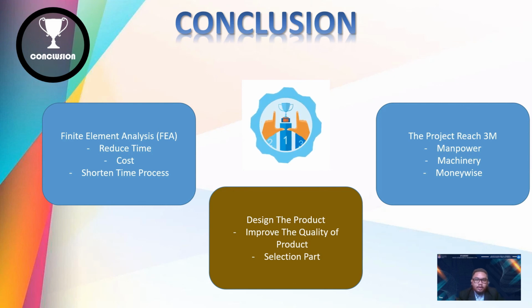Lastly, for the recommendation, the design and material selection also need to be considered and redesigned again to improve the quality of the product, because the current material used is PLA 3D print filament, which is only suitable for light applications. However, heavy duty use needs a change of material to prevent deformation of the product.